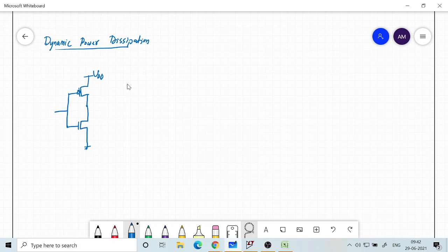Both of their gates are shorted, and that is where we give the input, and input varies as a function of time, and we looked at what happens to C out. Now I am putting C out, all the capacitance associated with the PMOS and NMOS, there are parasitics, and there is CL, all put together. I have included it in the C out.